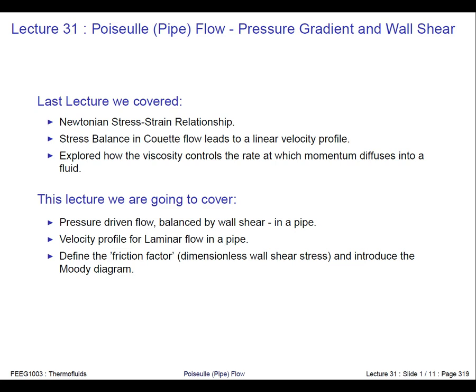And we start thinking about what the friction factor is. This is effectively the wall shear stress, which is related to the pressure drop, and this allows us to work out what this friction factor is that we introduced 2 lectures ago in the steady mechanical energy equation.